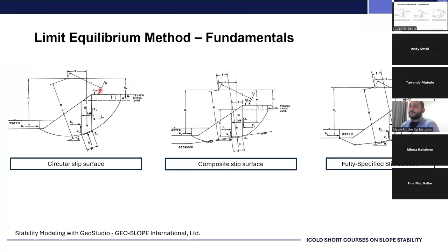And if you look into all those forces and do an equilibrium calculation, you can look into horizontal equilibrium, you can do moment equilibrium, and you can come up with the factor of safety for the whole slip surface and see what is the relationship between the shear strength of those soils and the shear stress that's mobilizing that surface.